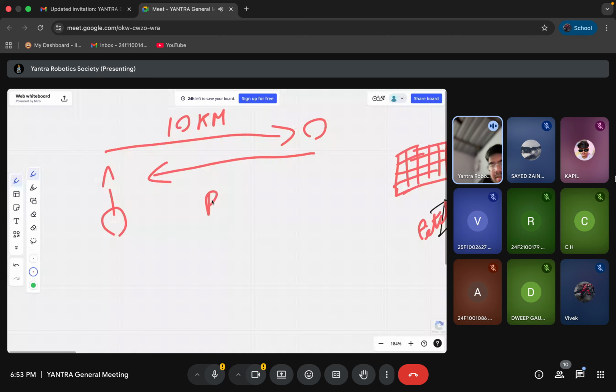In this case, you should have RTH set up. RTH stands for return to home. So in your Radiomaster Pocket transmitter, you can just assign one switch. Also, one more thing: which firmware are you using? Mostly you're using Betaflight, I think.